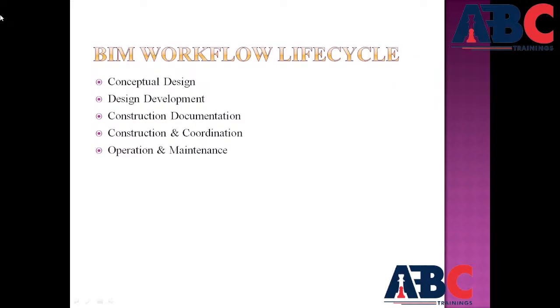At this stage the data input is minimal, but the foundation for the BIM model begins from that stage. So early 3D conceptual modeling is done in that. Feasibility and site analysis can be done. Basic volume and area calculations are done. And initial visualizations for client representations can be done. The tools used for the BIM workflow life cycle are like SketchUp, Revit conceptual massing, or ArchiCAD conceptual design. Next one is the design development.